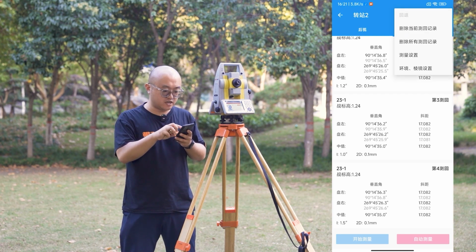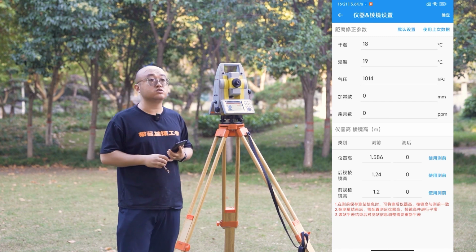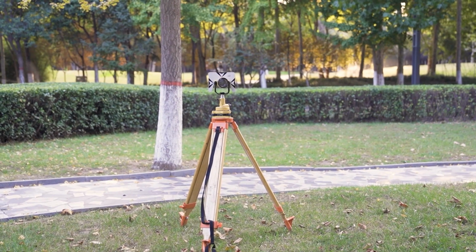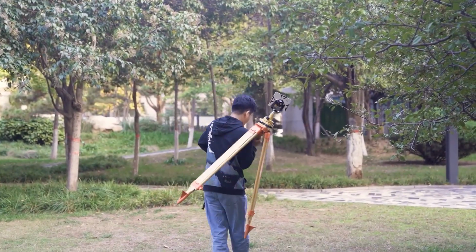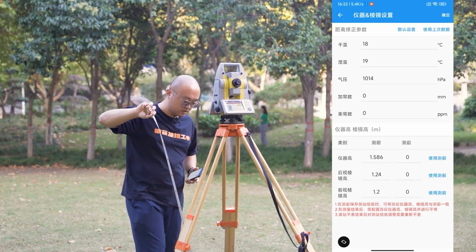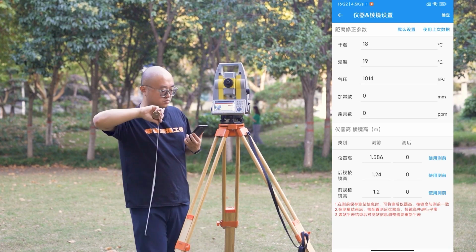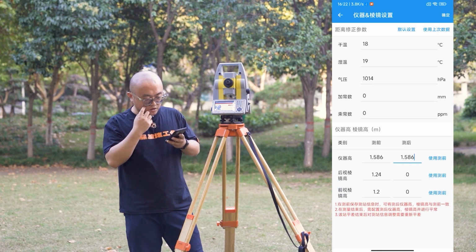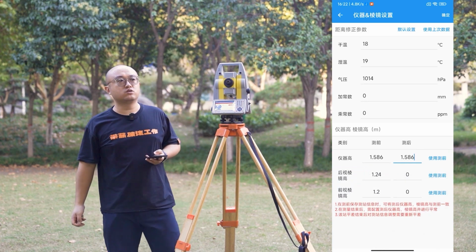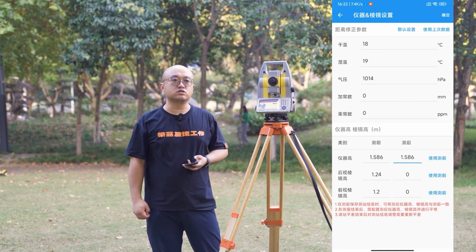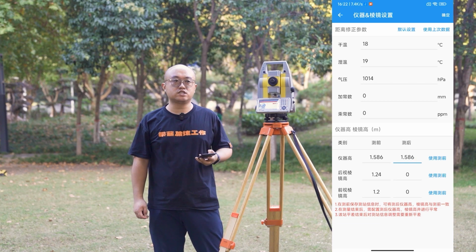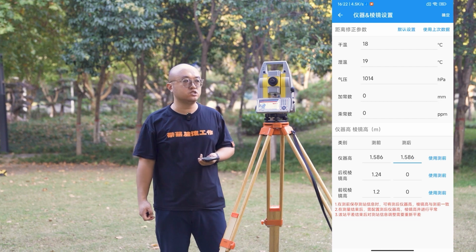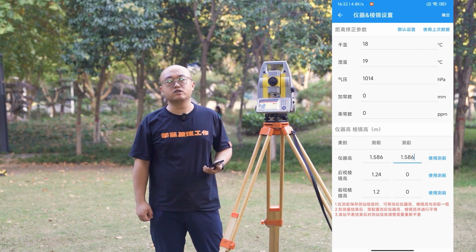Finally, before moving the station, it is necessary to record another piece of information, which is to record the height of the instrument again. Then, when two prisms are moving the station, their prism heights need to be recorded again without any difference. Why do we need to record it twice? Because according to the requirements in the specifications, if the height before and after measurement exceeds 3 mm, the software will remind you. Your data can still be exported normally, but it will only remind you. Because your height changes too quickly, it indicates that your station may have an installation problem, and the accuracy is not ideal. You can consider observing this station again, and then click OK.